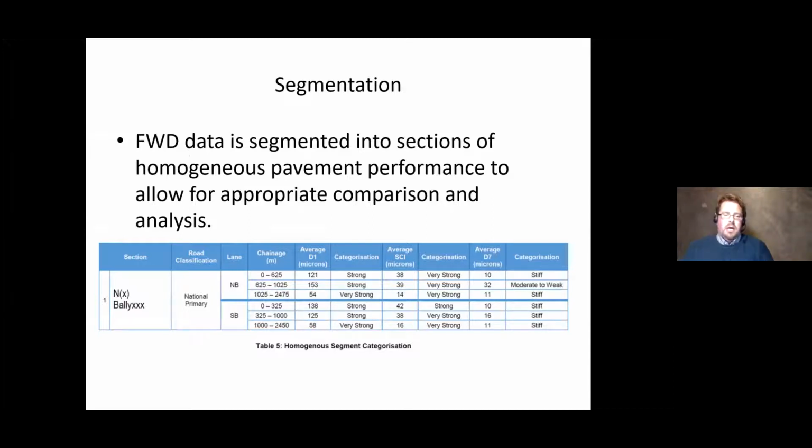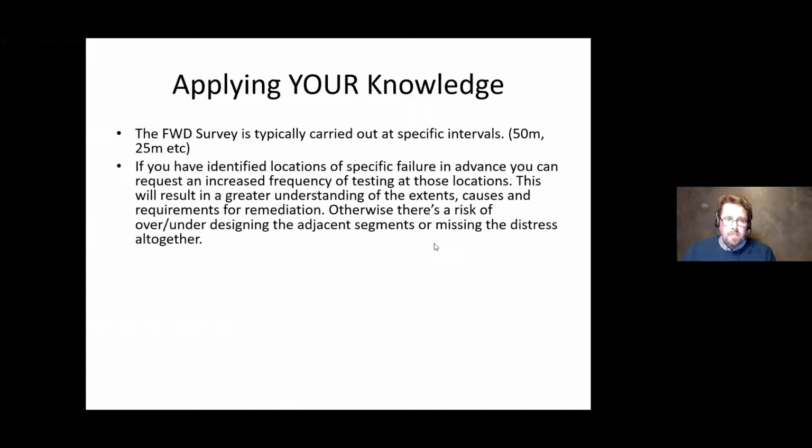analysis based upon those. And as you'll see here, this particular aspect they've shown the split into 600-meter sections. The 600 meters, another 500 meters, and these are based upon homogeneous behavior, so that when they go to do the design, they can design for sections of length as opposed to designing for every single location, which would not make it constructible. So when you go to hire your FWD, it's very important that you apply your knowledge.